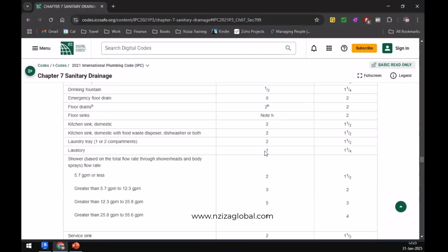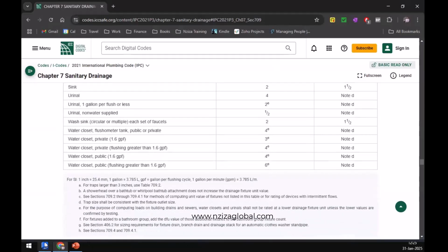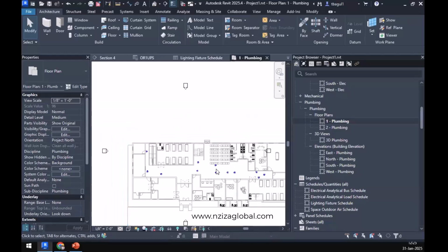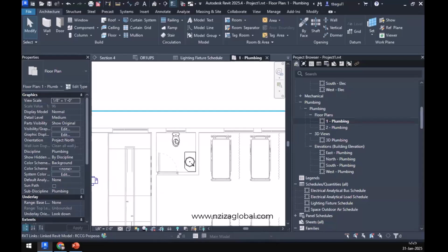All right. So now what we need to do is we need to add. If we start drawing a pipe from here, we need to understand how big the pipe needs to be, right? So for that, we'll start counting the DFUs from this point and we'll try to get it to exit the building at this point. All right. So now we have DFU of 6 assigned to this one and DFU 1 assigned for the lavatory. A total of 7 DFUs. Is everyone with me till now?